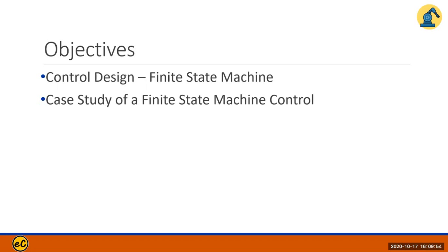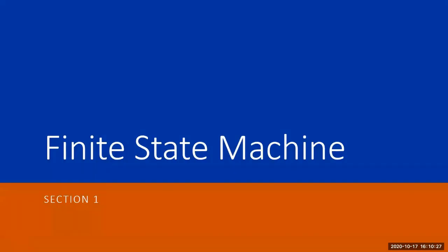The previous two approaches, Model Plan Action Approach and Behavioral Control Approach, both will require a processor, and the behavioral approach may need a multi-threading environment, and the model plan action may require a CPU or a neural network. And right here, this finite state machine can be a simple design, just some ASIC design would be good enough. So it represents a simpler ASIC approach for control.